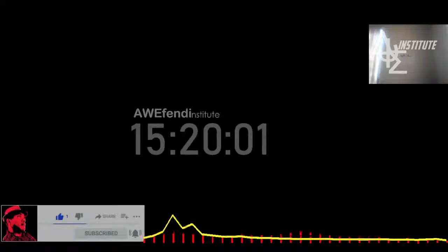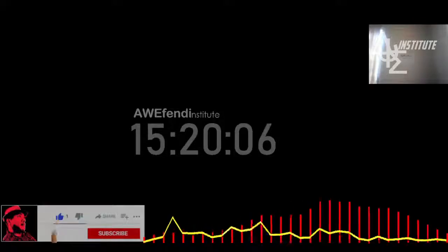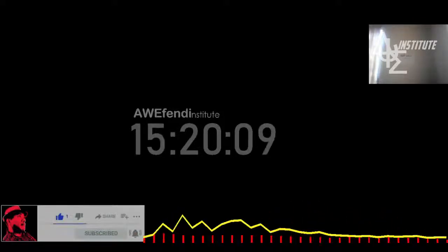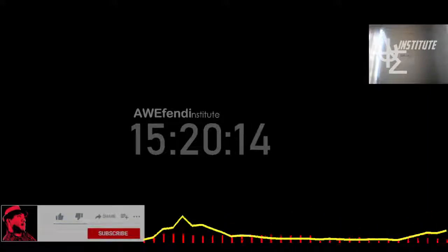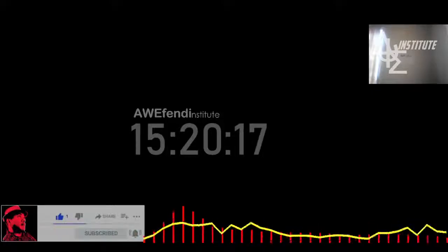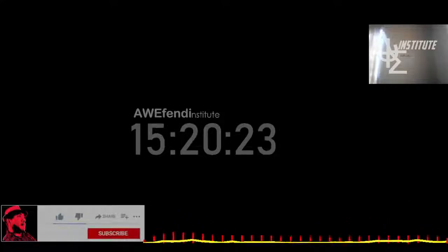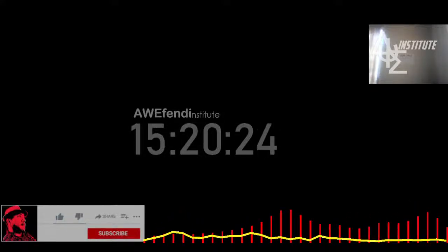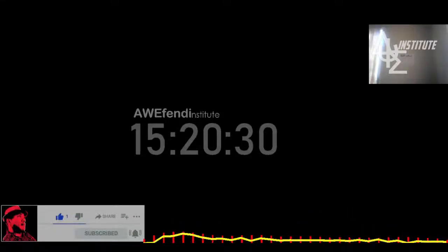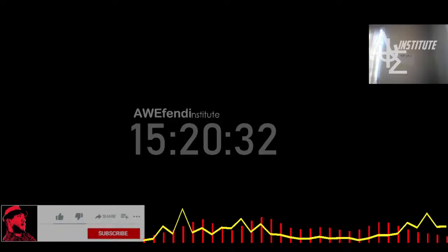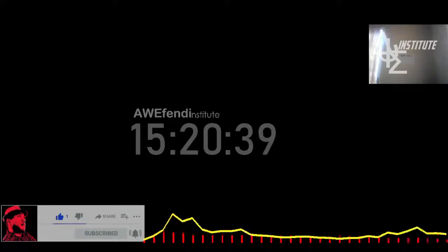I'm going to update the volume in context, so we get an immediate fluid volume update based on the geometrical change of the solid. And here we can see how that impacts our fluid flow. Looks a bit better. Of course, this big recirculation zone here that we had before is not there anymore. We can look in terms of pressure drop. Yep, it went up. Since we're adding more obstacles between inlet and outlet, you need a little bit more power to pump water through this system. Then we have the vertical ribs. So let me update the fluid volume in context again.